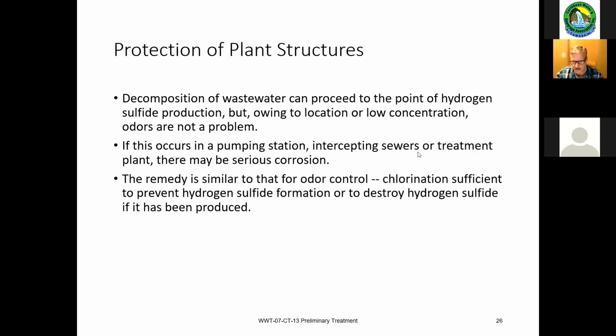Just looking for any questions. Good question: what kind of gases are there in the odor? Is it just H2S or are there other gases as well? The majority you're going to find in sewer systems is H2S. If you are dealing with discharge from industries, there may be other things in there as well, but hydrogen sulfide is the main one that you're going to see.